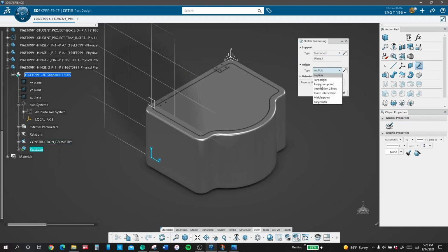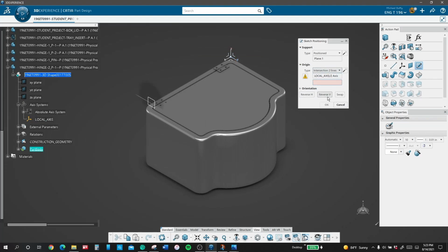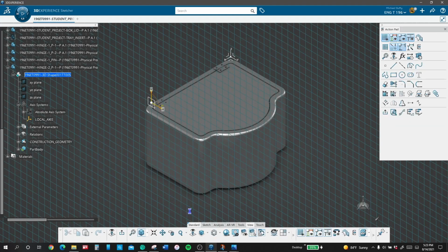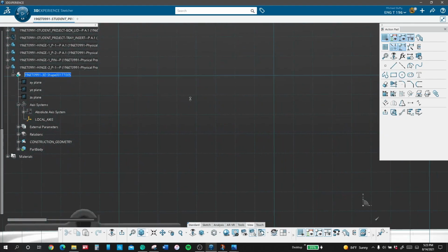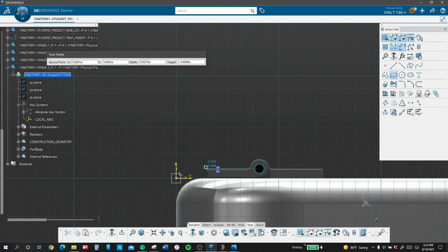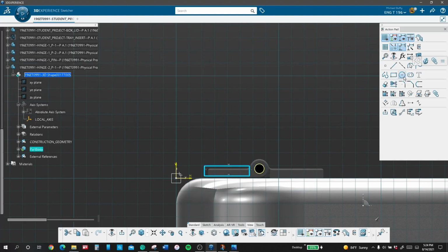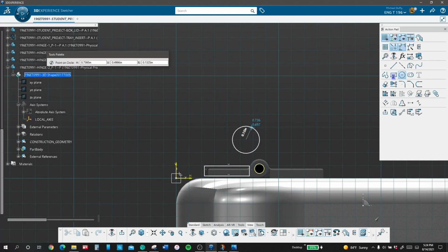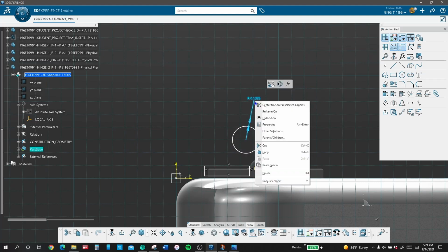Now, selecting sketch plane. And we're sketching right on that plane that I just created. You can see I already have one hinge made. Now I'm just going to demonstrate how I did it. Let's start with a circle, and a rectangle, and another circle. And that's the basic outline of the hinge right there.